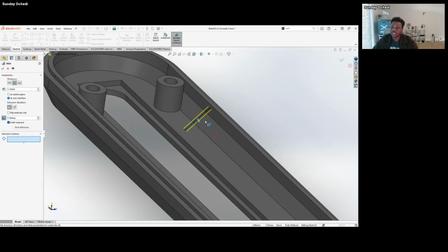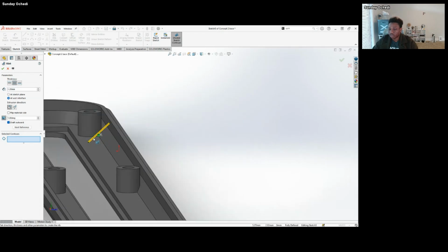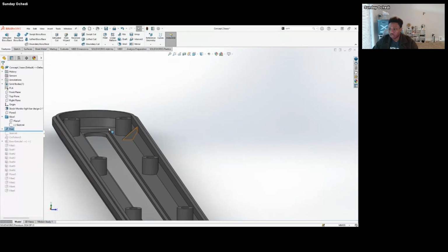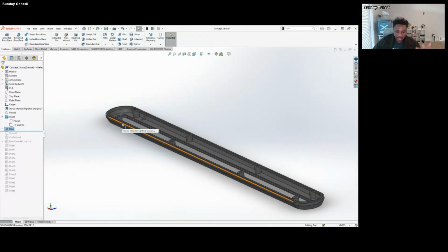You can also design it yourself, just use your normal extruded boss and stuff, but the rib tool makes it simple because all you have to do is have a line that connects what you want, and then the rib tool can be used to help you do what you want. But this is slightly advanced. With time, over your years of practice, you get to use them in things you want to do, and you might not really use them often.